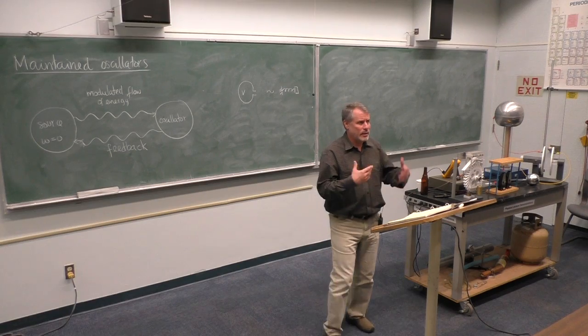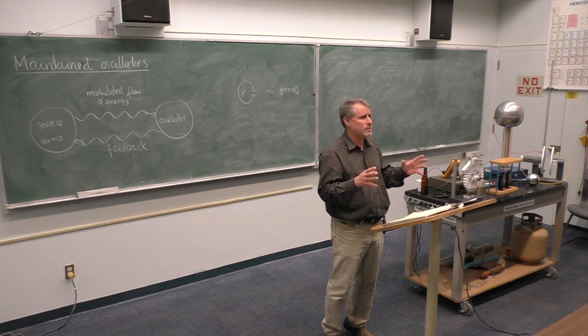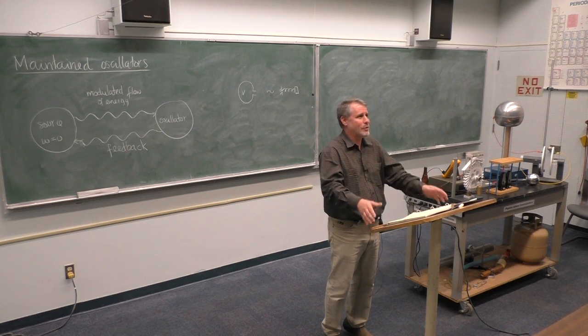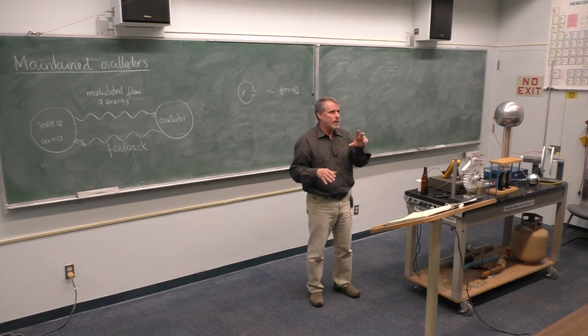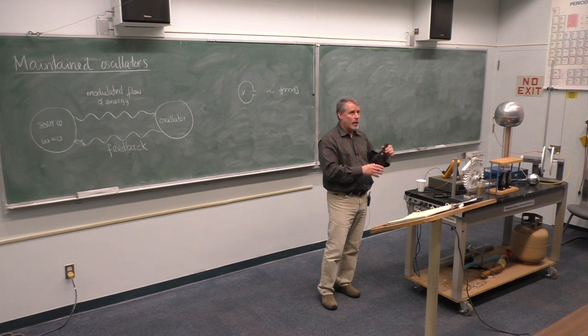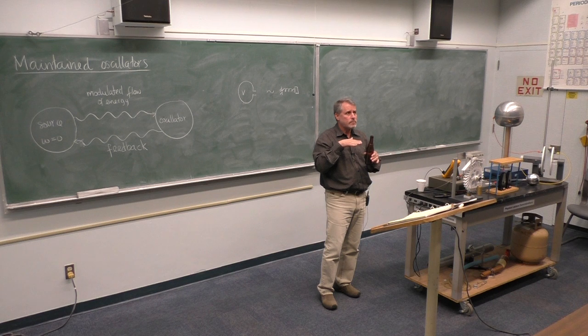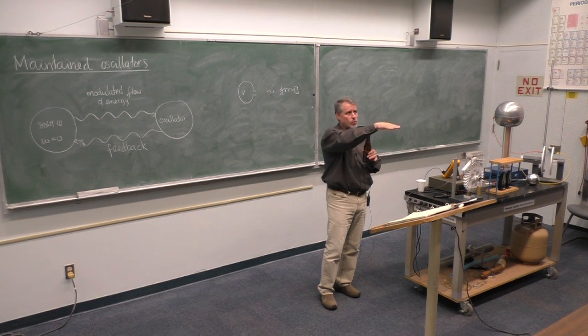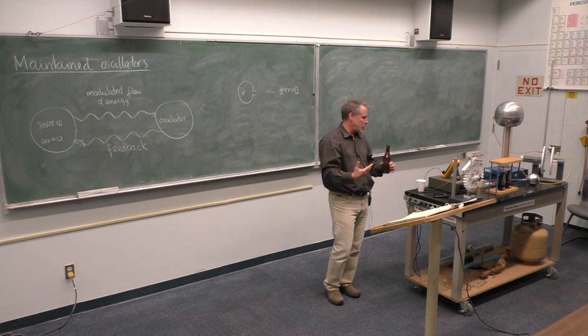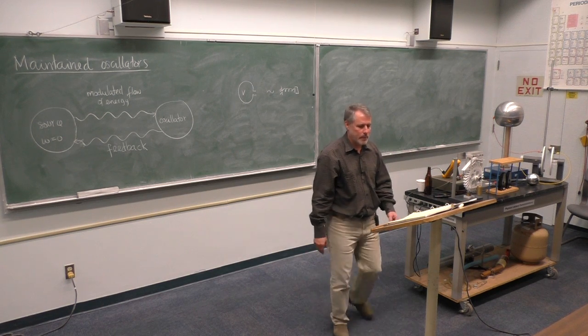The excitation mechanism of the Helmholtz resonator is actually a very hard thing to understand. There's ongoing research on that. But just as a first approach to try to understand this, the blowing of air through the neck generates vortex shedding. There are vortices that are being shed as the airflow goes through, and the way they are shed is going to be modulated by the resonant frequency of the resonator. So it is a complicated mechanism, but fundamentally the root of the modulation of energy is coming from vortex shedding. Okay, so that is one example of a maintained oscillator.